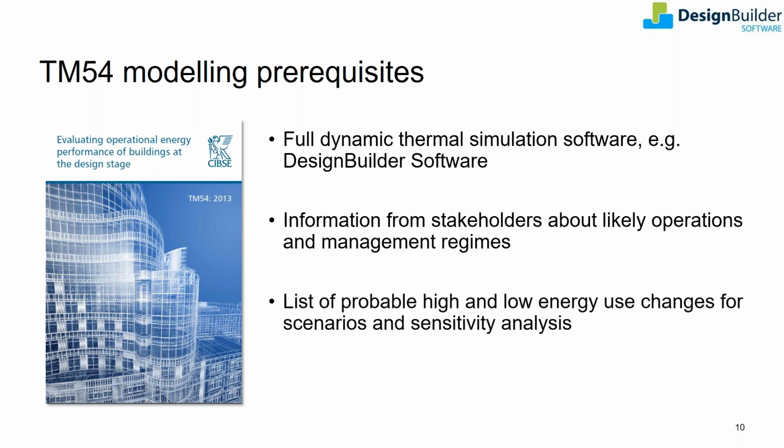During those discussions, identify the parameters that might change over time or are too difficult to accurately assume at this stage, such as weather, occupancy, and system efficiency reduction. These will help in scenario and sensitivity analysis. Finally, identify the relevant benchmarks to compare the building against, such as those given in TM46 or CIBSE Guide F.